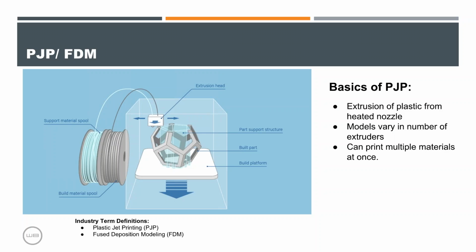And it can also produce prints with multiple materials. So what's the benefit of that, right? So the benefit of being able to do things with multiple materials is that it opens up the door to multiple supports and or just multiple material properties in one part. The amount of printers that can actually produce multiple materials in one print in this realm is not as popular as the ones that just print one material across the board, but it is available. And again, the benefits are, more than anything, really soluble supports, and then in other cases, multiple material properties, but those are a little bit of a niche.